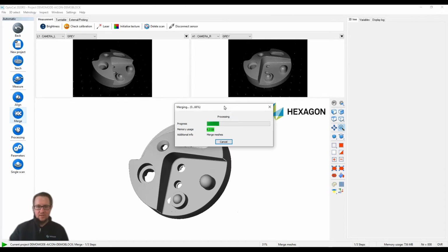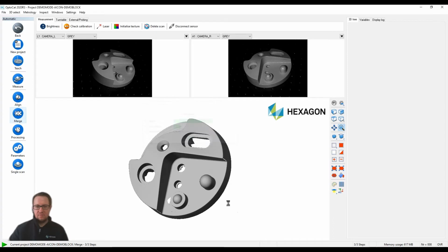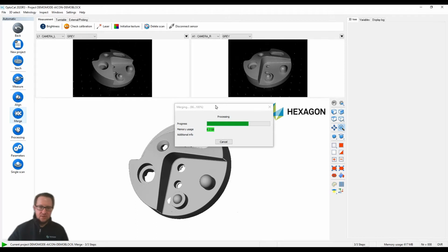And once this is done, we'll go ahead, load the CAD file, and do a quick inspection and report, and remerge the file again, just assuming that we scanned a different part, and PC-DMIS will run through the inspection with the new STL file. Alright, this is almost done.